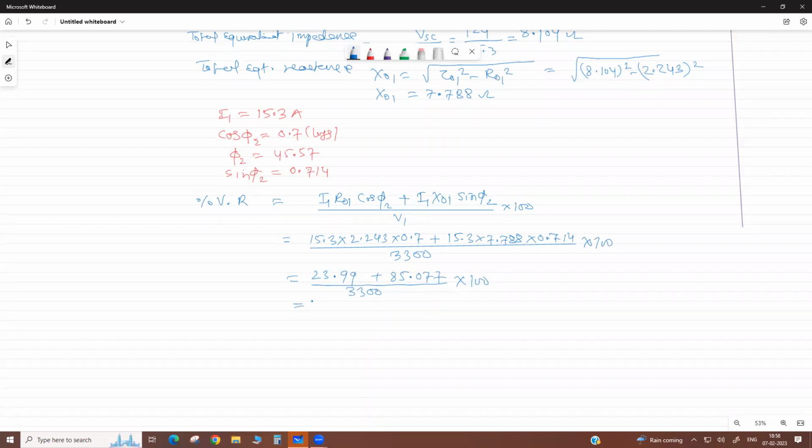3.99 divided by 3300, 3300 only. My dear, it comes 3.305%. This is your voltage regulation, percentage voltage regulation, okay.